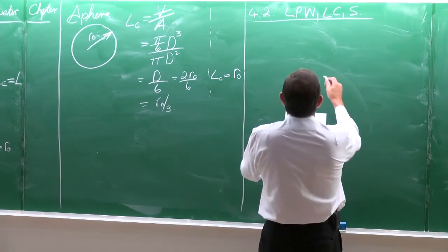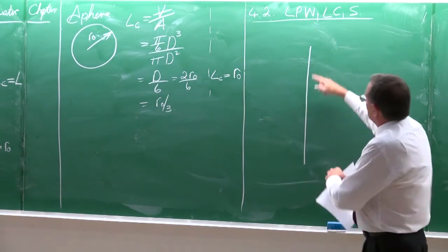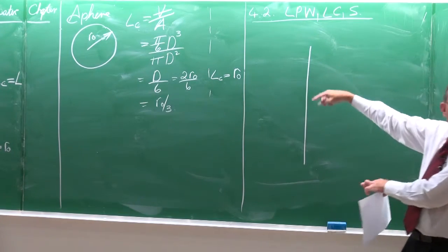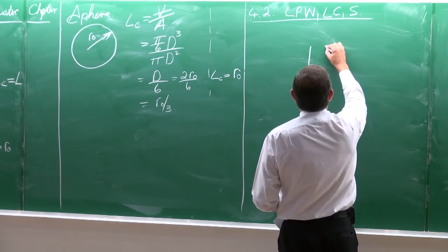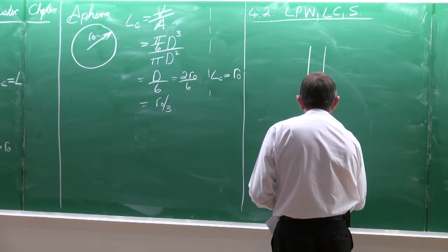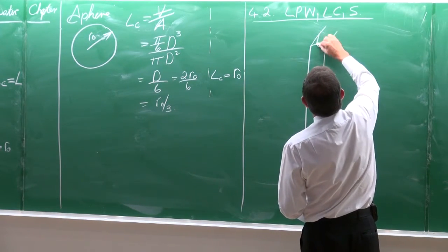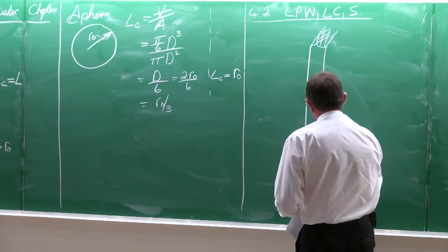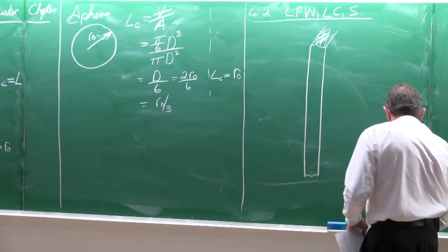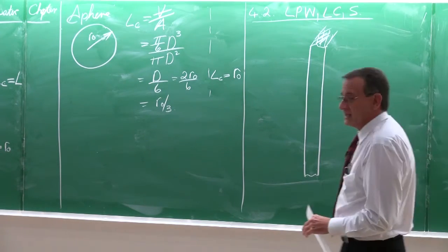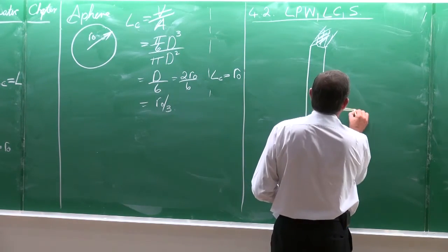Right, so let's consider again the long plane wall and make the line longer on your page, because it's very important to remember the dimensions that we're talking of here is long. Okay, and through here, this is insulated and that is insulated, and the result is that the heat transfer rate, as I've previously said, is in one direction only.